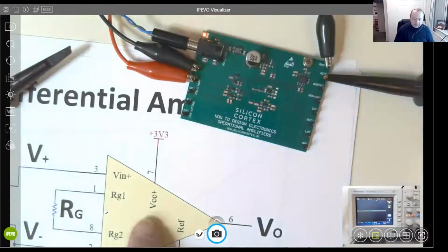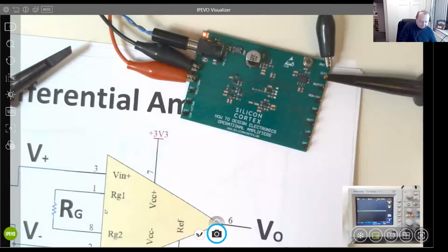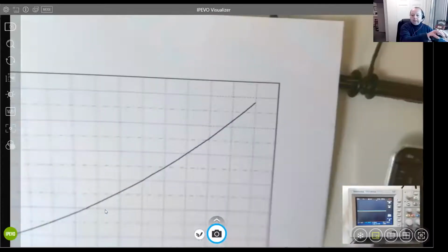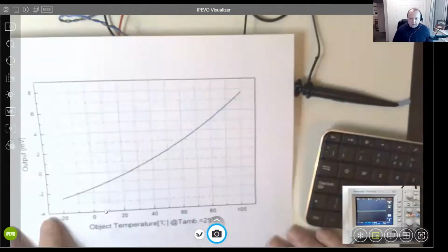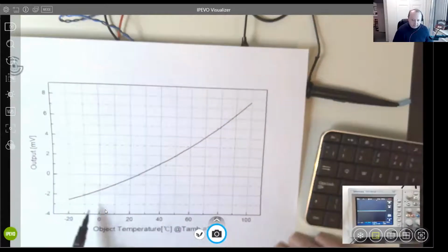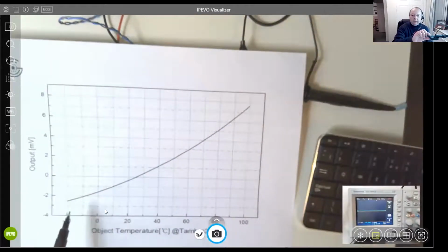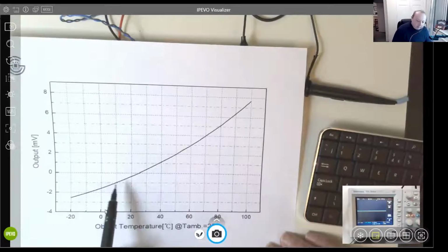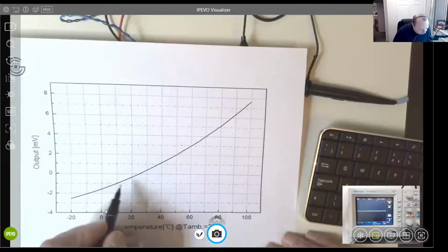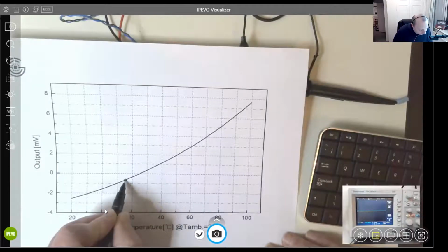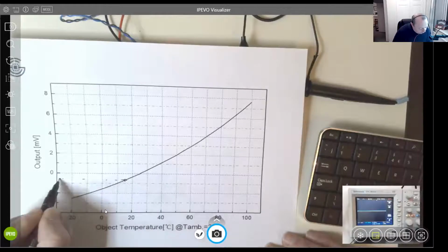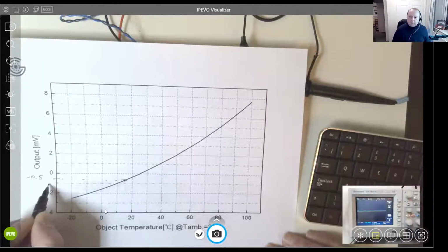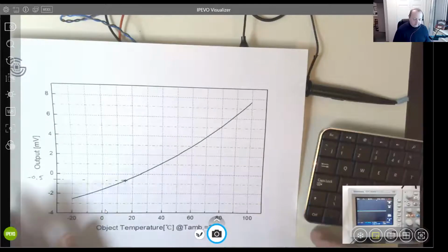But if you look at the data sheet for this sensor, which is here very conveniently, you'll see when you look at these types of sensors, they've got a very small output, depending on the voltage and the temperature. I mean, in here it's about 16 degrees. So I'm about at this point here. Yeah, so I've only got about minus 0.5 of a millivolt coming off that sensor.